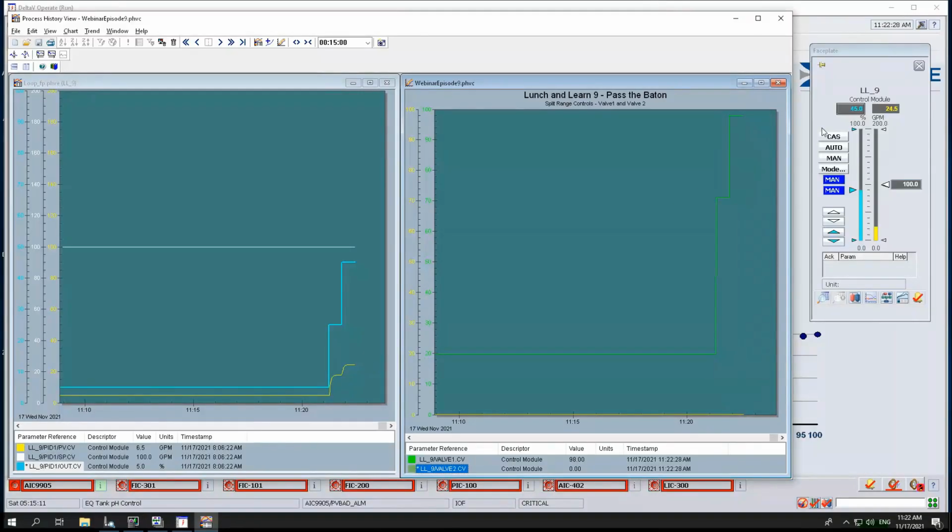I'm at 45% open. So now I'm going to go to 55% open. I'm going to cross over into the big valve territory. So I got to go to 55% open. And now the big valve started to open up. And you can see now I'm getting a much larger flow change.